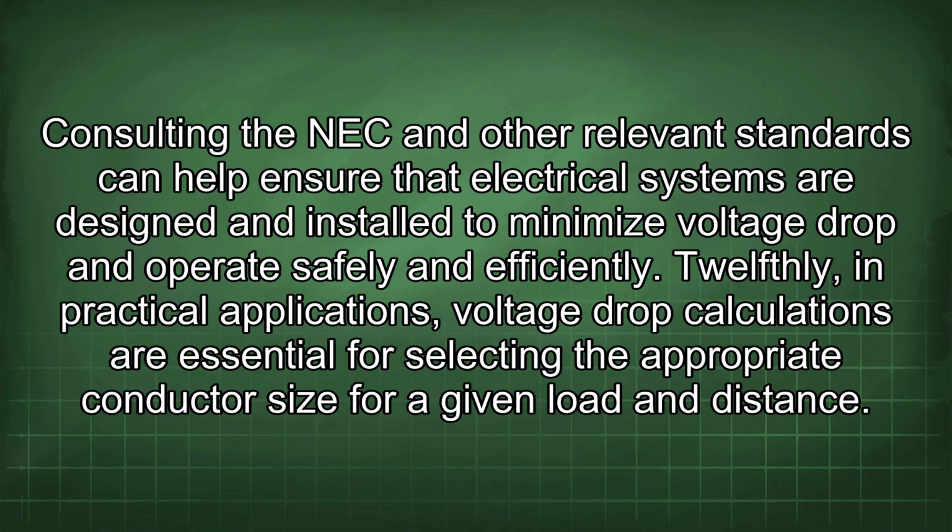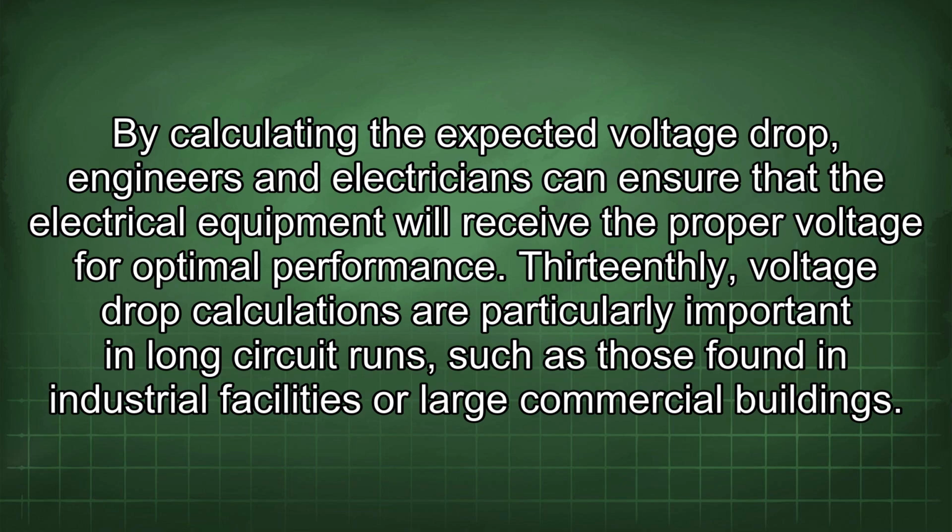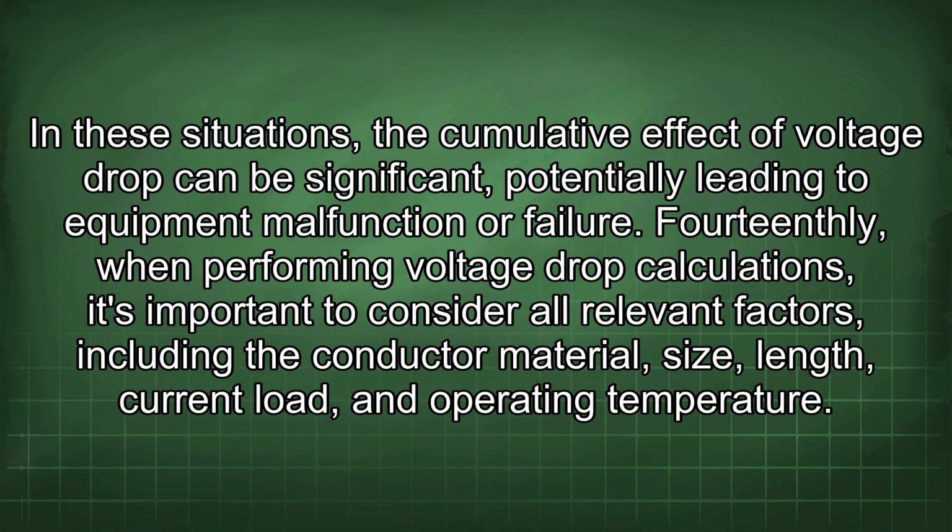12thly, in practical applications, voltage drop calculations are essential for selecting the appropriate conductor size for a given load and distance. By calculating the expected voltage drop, engineers and electricians can ensure that the electrical equipment will receive the proper voltage for optimal performance. 13thly, voltage drop calculations are particularly important in long circuit runs, such as those found in industrial facilities or large commercial buildings. In these situations, the cumulative effect of voltage drop can be significant, potentially leading to equipment malfunction or failure.